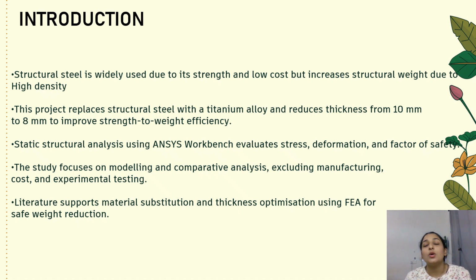Third one, static structural analysis using ANSYS Workbench evaluates stress, deformation, and factor of safety. So this analysis is actually using static structural. So I can analyze the von Mises stress, total deformation, and safety factor. The study actually focuses on modeling and comparative analysis, excluding manufacturing cost and experimental testing.